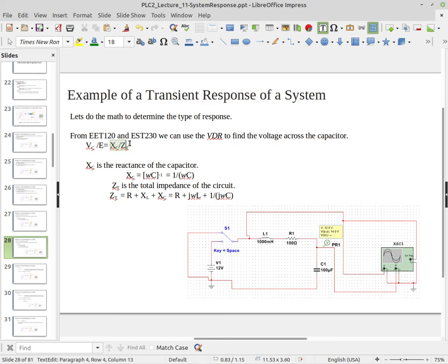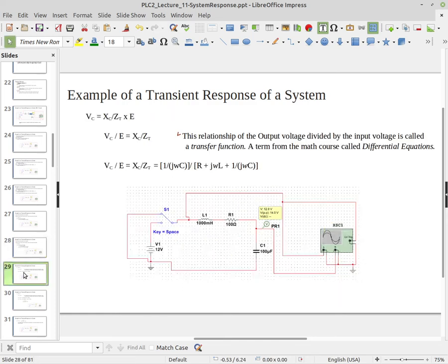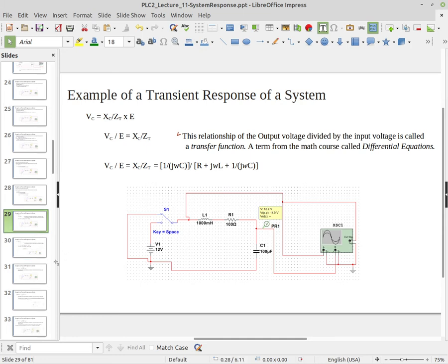And so this is just an impedance. You've done this 100 times in AC circuits, calculating the voltage across the capacitor or some other element in the circuit. And that's all this is. This is just the voltage divider rule here. But this voltage divider rule we call the transfer function. Now notice this has this omega in it.